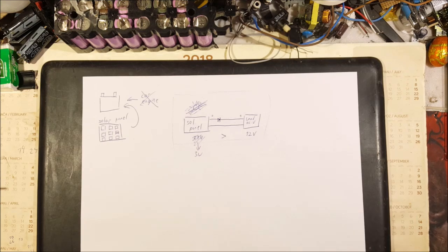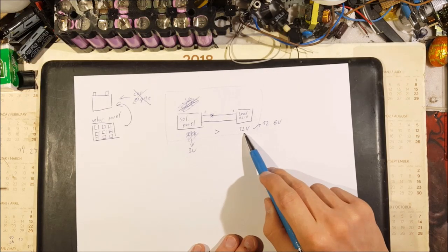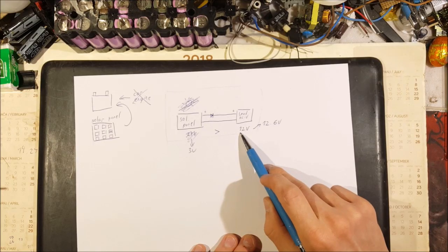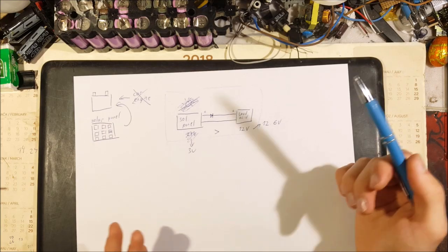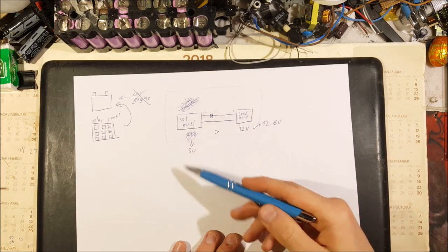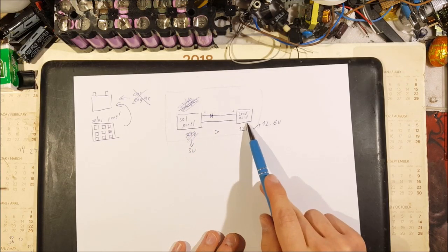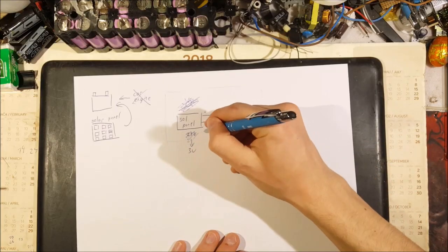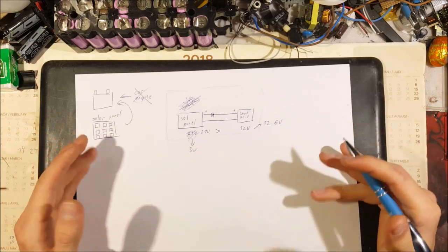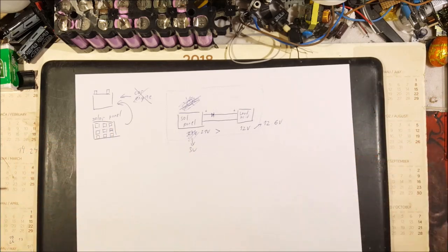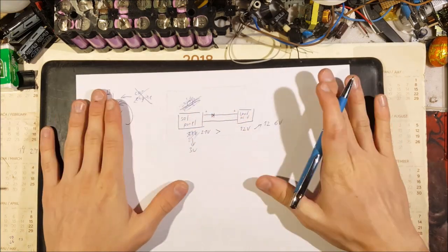But wait, there's more. Since this is a lead acid battery, as it charges, its voltage will rise from 12 volts to 12.6 volts, and since there is nothing to limit the solar panel from keeping charging it all the way up to the previously mentioned 21 volts, there is nothing to save our battery from overcharging. Now, since this circuit is fantastically simple,